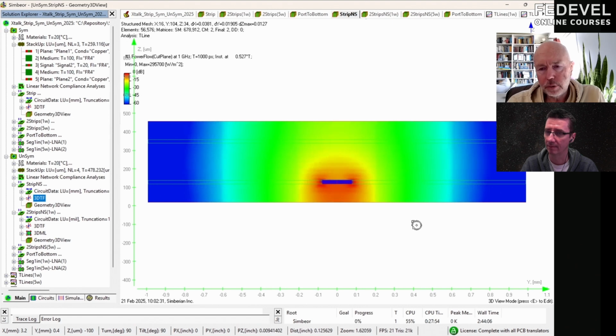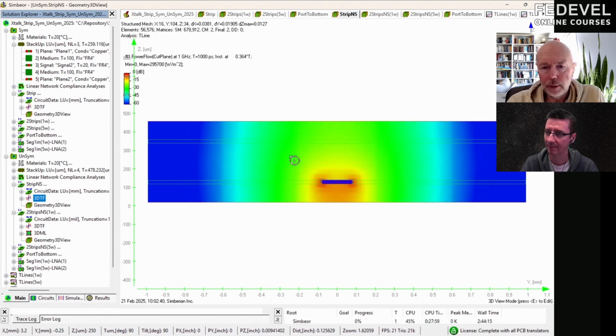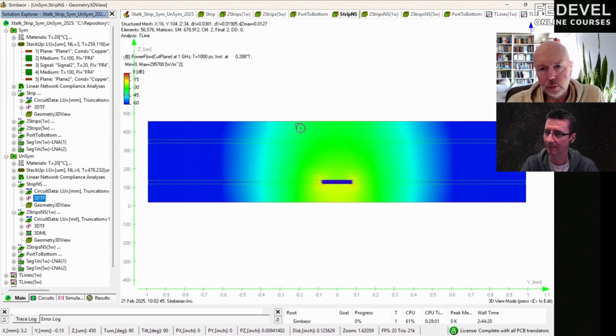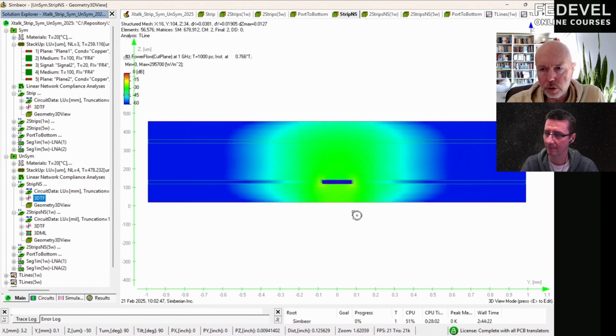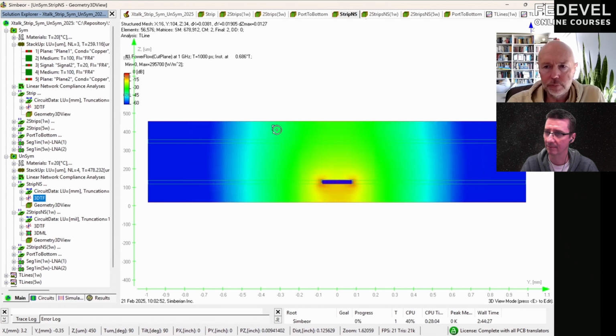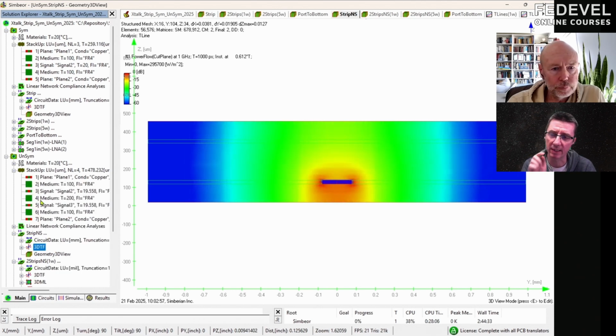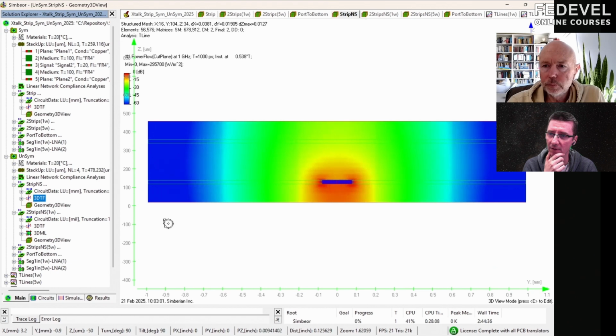Right here, spread is more visible, right? And the reason is because there is a remote plane, and the remote plane has, in this case, only about 1/4 of the currents compared to this plane, but they're still there. And I think you mentioned there is an advantage when it is in the middle. You mentioned something about canceling some of the crosstalk, or am I wrong?